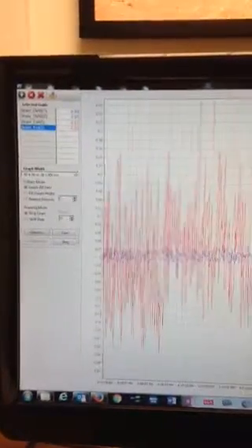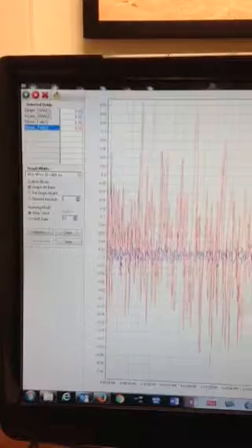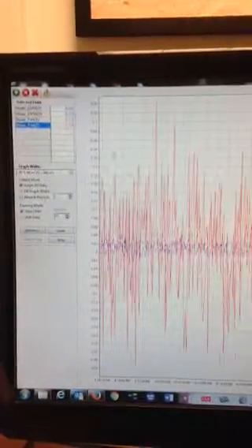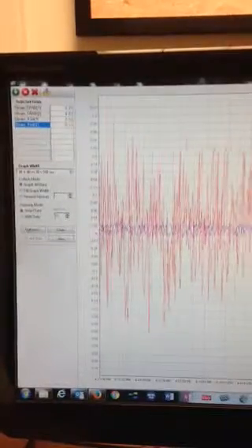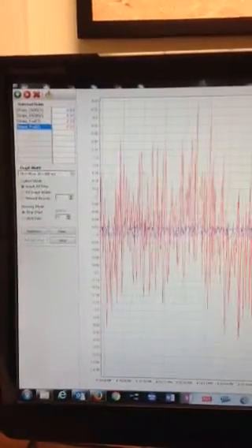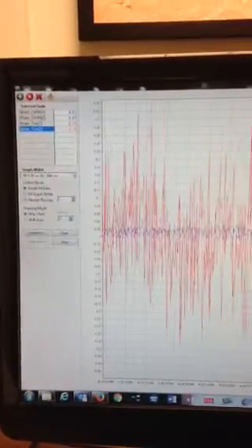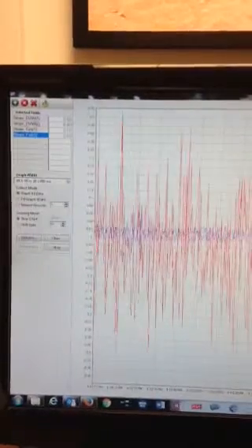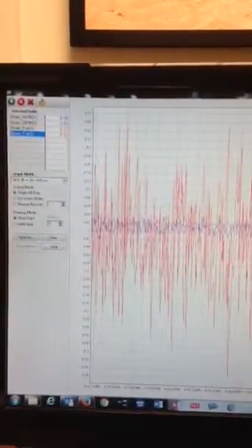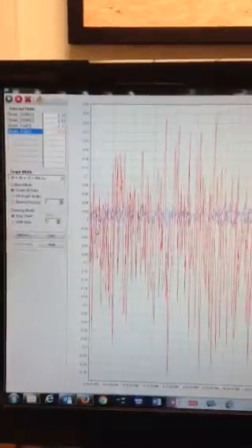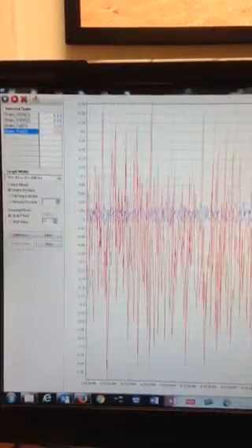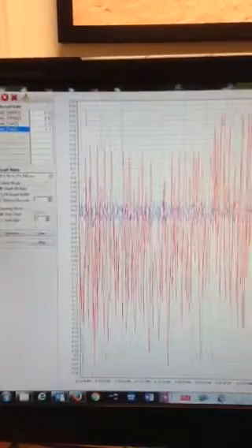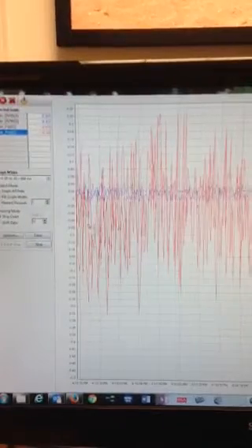And what we see from this is that the noise from the bonded foil gauges ranges, starting from 0, to as high as 0.34 microstrain. The range is approximately negative 0.3 to positive 0.3 microstrain. The range on the vibrating wire data is approximately negative 0.02 to positive 0.04 microstrain, so about an order of magnitude less on the noise.